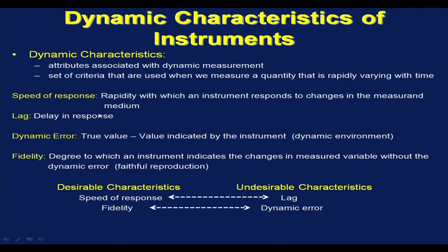So, speed of response is the rapidity with which an instrument responds to changes in the measuring medium, while lag is delay in response. So, speed of response is a desirable dynamic characteristic, while obviously lag, which represents delay in response, is an undesirable dynamic characteristic.